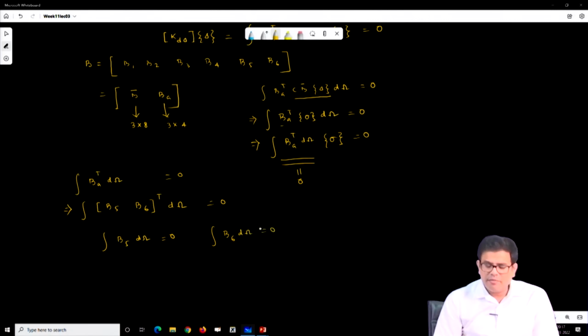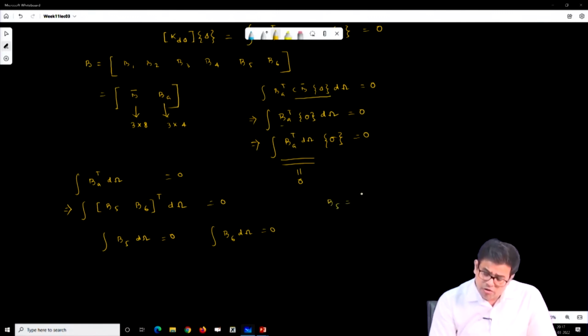Now B5 and B6 are what? B5 is essentially, if you write the B matrix, phi5 comma x, 0, 0, phi5 comma y, phi5 comma y, phi5 comma x.